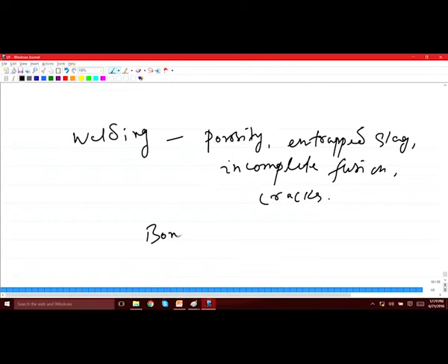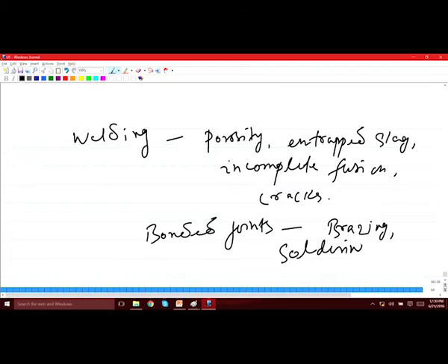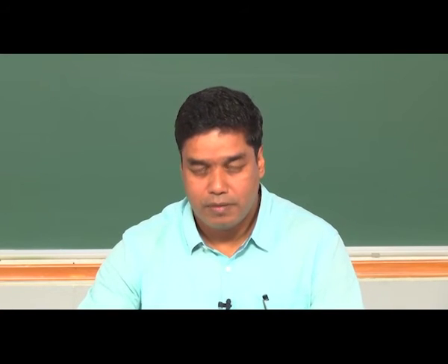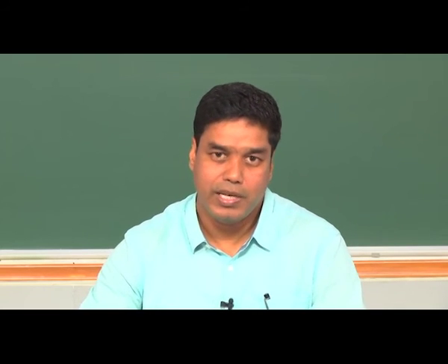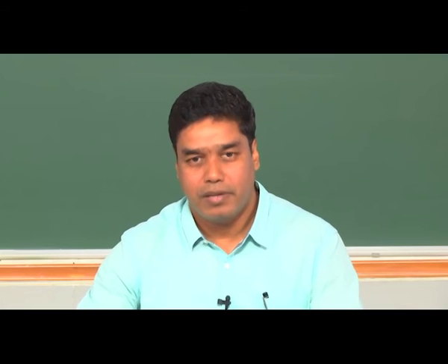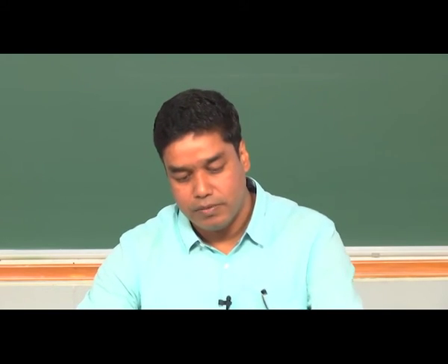Then bonded joints also, to find out the soundness of the joint, whether the joint is good or not. There again ultrasonic testing is very useful, like if you have these brazed or soldered joints, or adhesive bonding. So, in all these cases, in order to find out whether the bonding is good or not, ultrasonic testing can be utilized. Okay. So, these are some of the applications of the technique. There are many more, but these are some of them.